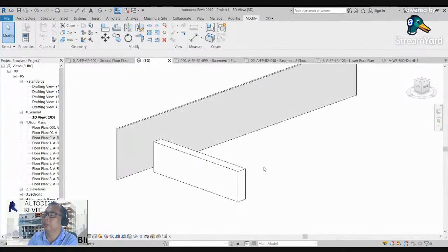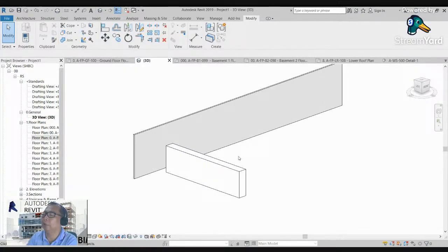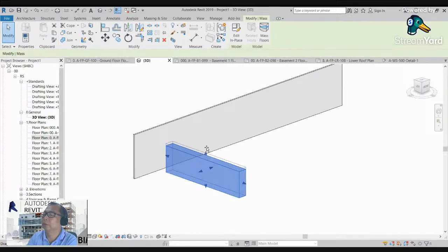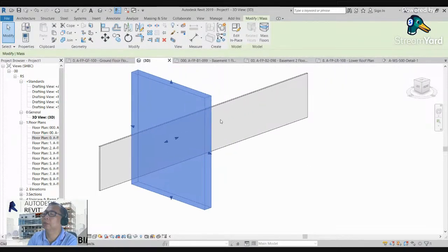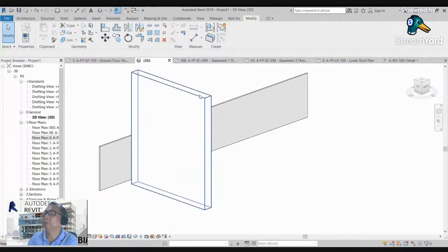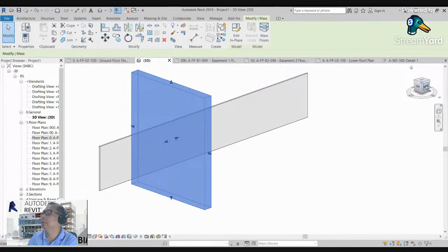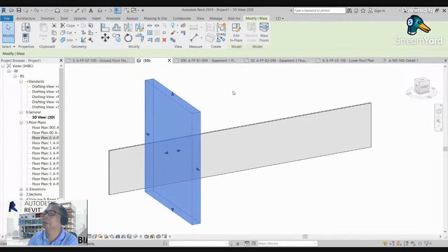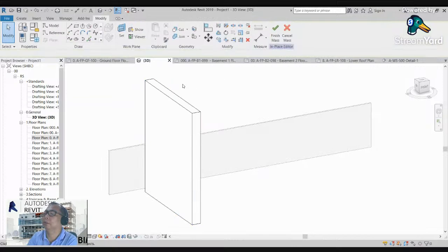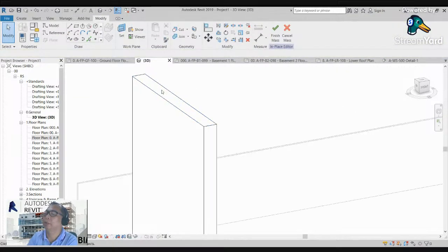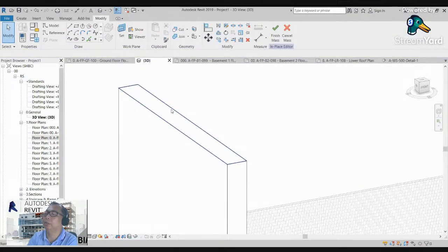You will see that is the massing, no? We will create an inclined wall. Just click that and drag going up, and then this one, edit in place, and then you will notice all the sides highlighted.